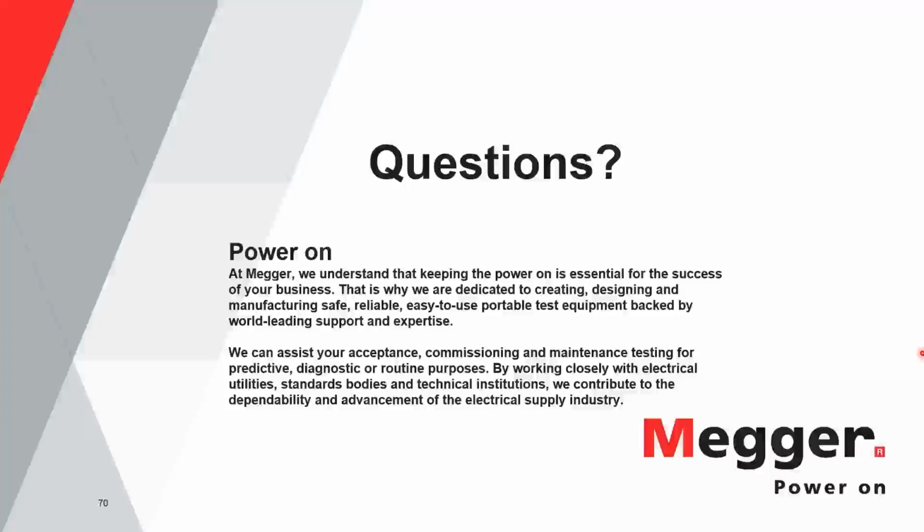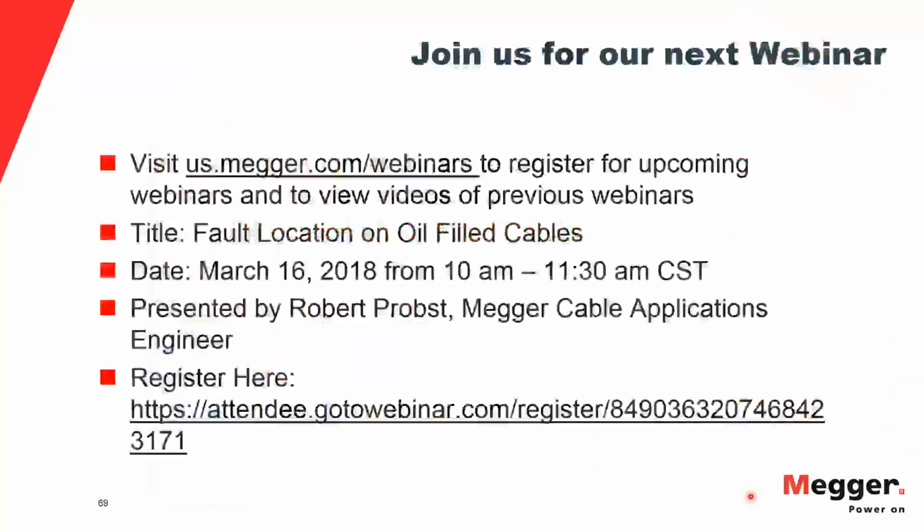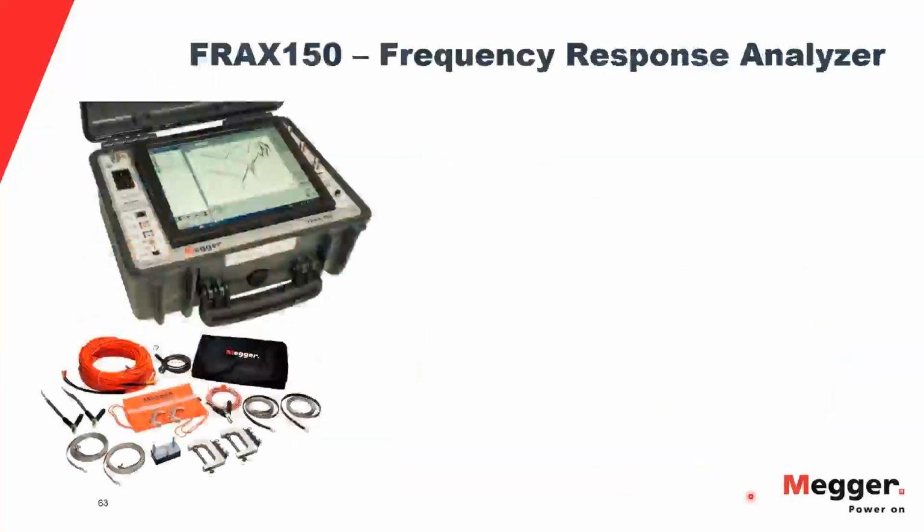It's not bad to run it on all of the taps. You can see specific situations on each tap, but it's not fully necessary. On the de-energized tap changer, once the transformer gets in service, you usually don't move that tap. They could have used the transformer in tap number 3, let's say, or tap number 2, and for any reason during commissioning, it was only tested on the nominal tap.